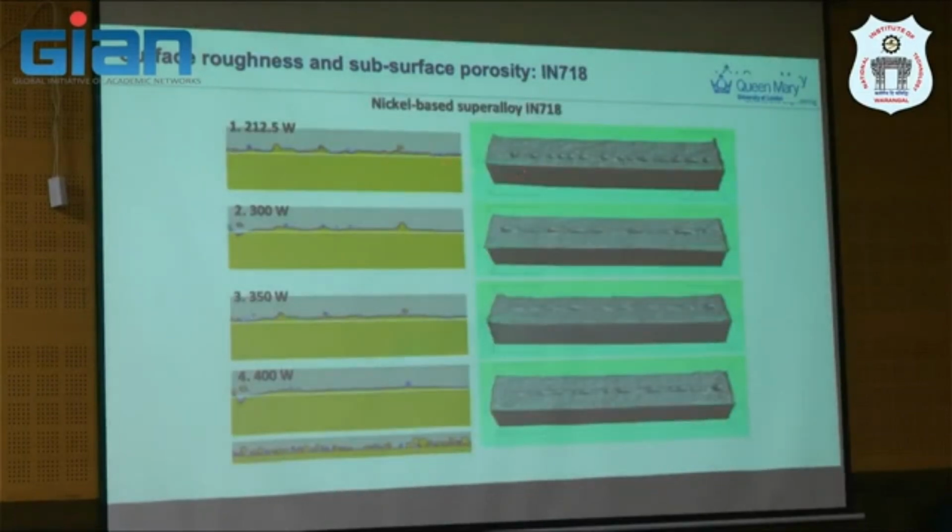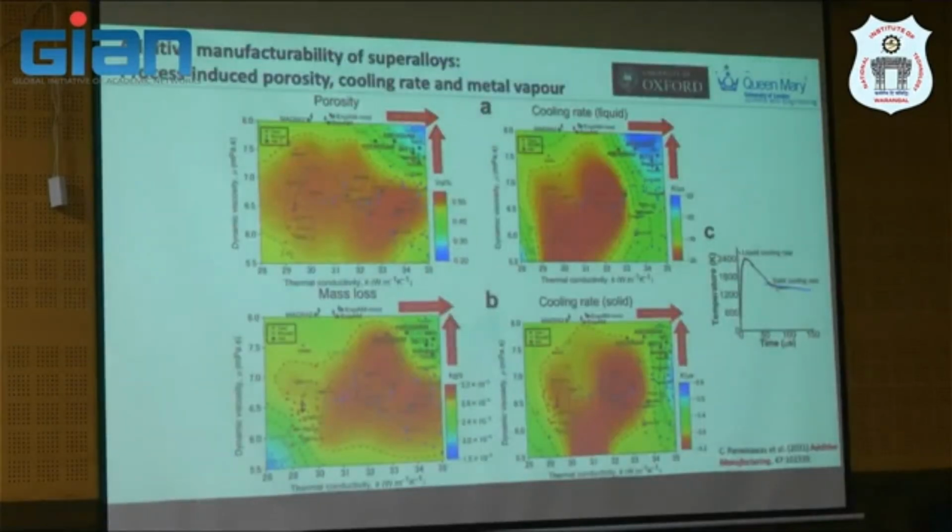And then this is where the roughness we actually tested in the nickel-based superalloy, previously in titanium 6-4, using micro CT. Again, this is a single track, this is balling, quite rough. Again, and then subsequently you will see it's probably a smoother surface, but not ideal.